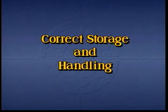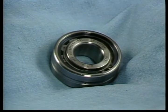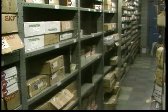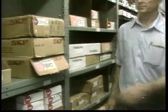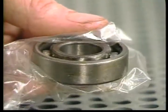Now, in addition to installing bearings properly, it's also important to store and handle them correctly. Occasionally, a bearing will fail due to damage that occurred even before it was installed. Bearings should not be stored in areas subject to dampness, vibration, magnetization, or extreme changes in temperature. New bearings should be kept wrapped and in their original box until you're ready to install them. New bearings should not be handled more than is absolutely necessary.